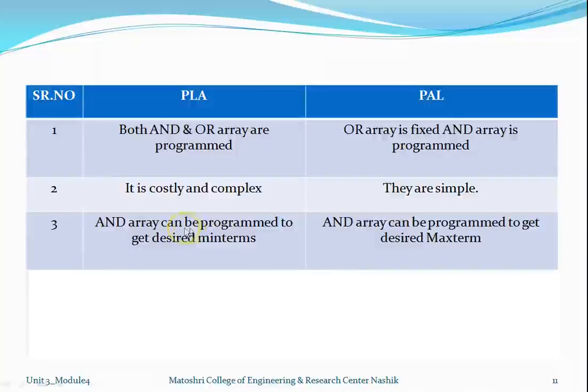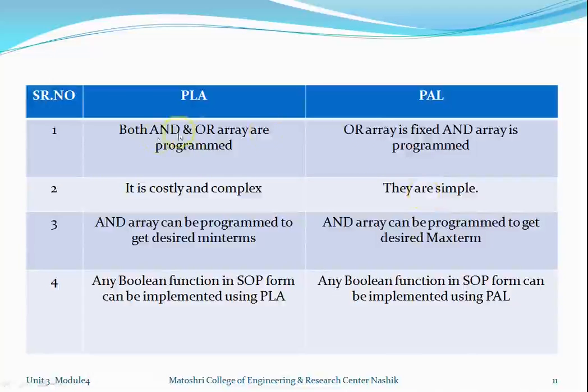The PLA AND array can be programmed to get desired minterms. Similarly, the PAL AND array can be programmed to get desired minterms as well. So any Boolean function in SOP form can be implemented using PLA. Similarly, SOP-form Boolean functions are implemented using PAL. Both are used to produce the basic functions of Boolean algebra in the form of SOP.